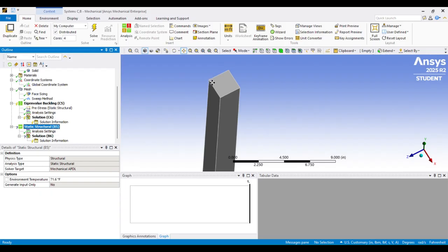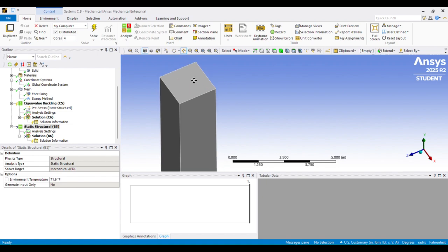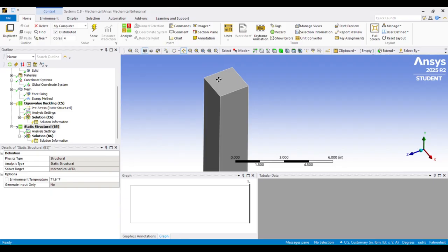Now I'm going to model this beam, trying to model the boundary conditions as close to the boundary conditions that are used in the Euler beam theory. So I'm going to try to model the boundary conditions as basically a fixed support with 1 degree of freedom in the rotational direction about the x-axis.